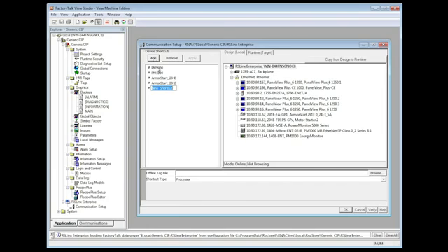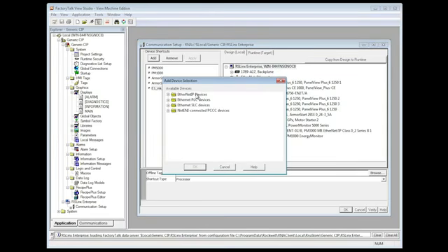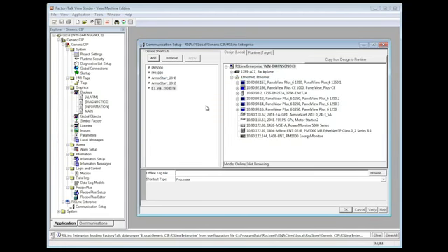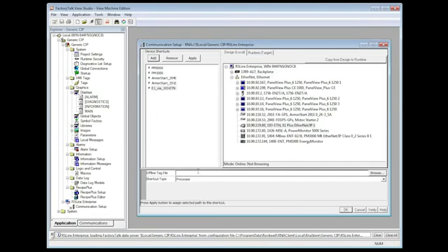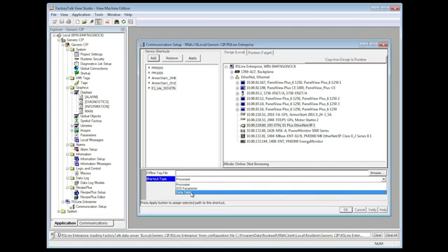Now we're adding an E1 Smart Overload Relay. The steps are the same. First, you add a shortcut, followed by the device on Ethernet IP, typing in an IP address, and then changing the shortcut type for an E1 to a data table.